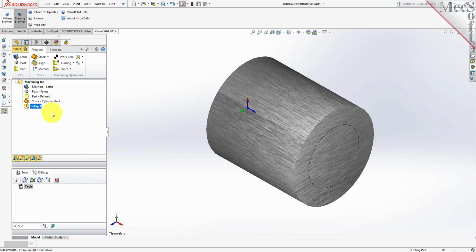They follow the convention that the spindle axis of rotation is designated as the Z-axis. Secondly, the axis perpendicular to this axis, along which the tool travels to cut into the stock, is designated as the X-axis. So the part and spindle rotate about the Z-axis, and moving the tool along the Z-axis provides the direction of feed, and moving it along the X-axis provides the depth of cut.